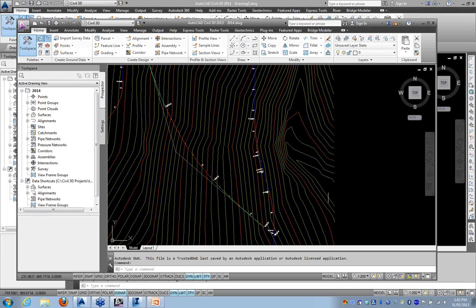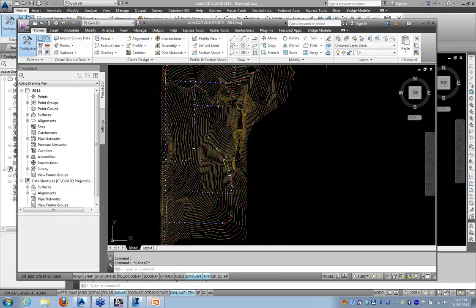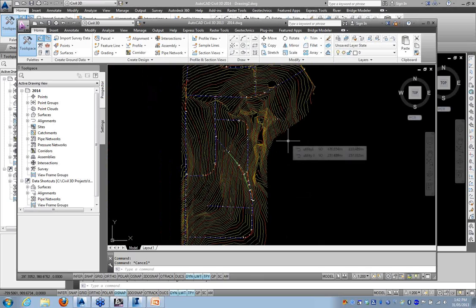All of these are editable, like they were created in 2013, so I can move that, for instance, across to there. Do anything else I want with it. The only proviso would be any types of objects that exist in 2014 that don't exist in 2013, they'll still be in a proxy state. But types of objects that exist in both versions will be editable in the previous.